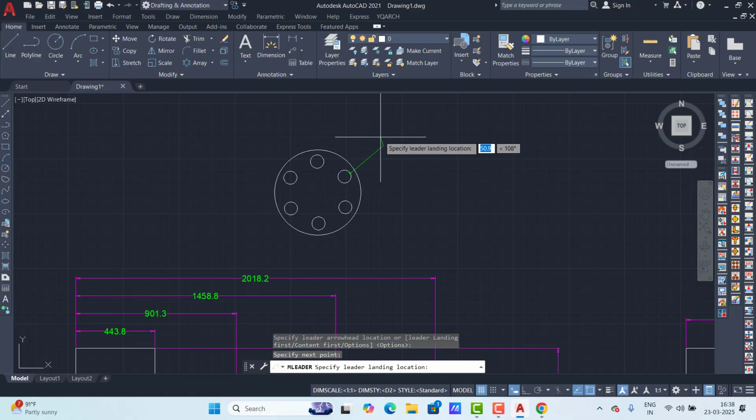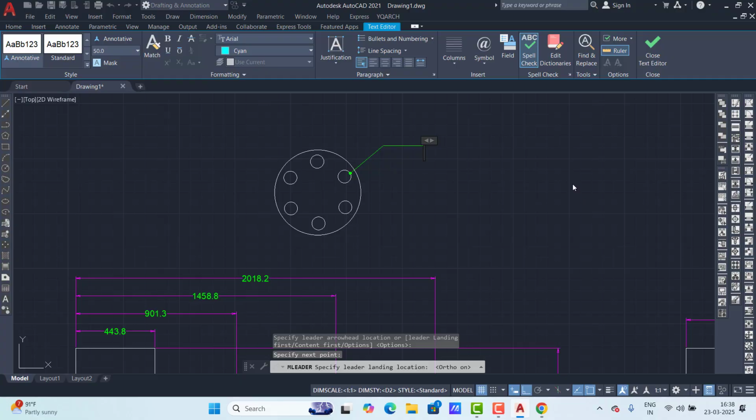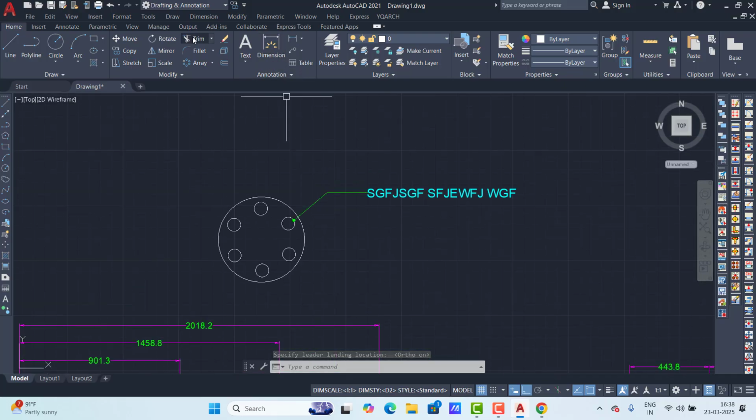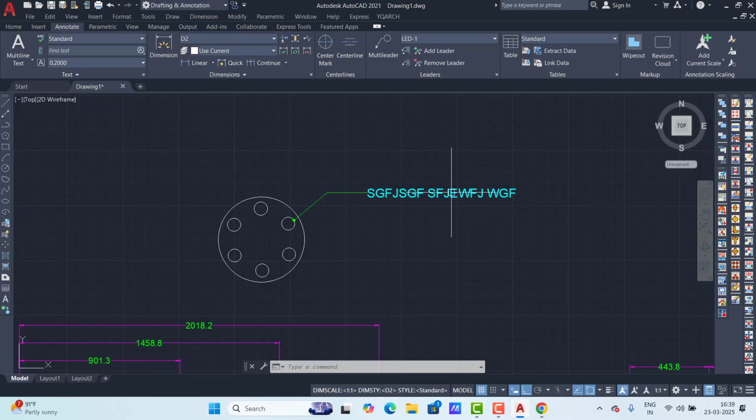So, 1075.5, give here 5. Okay, and for the upper limit here give 1076.4, and just press OK, and this box will be present here. That means that is the lower limit, that is the upper limit. So if this shaft length value is between these two values, then that is okay.